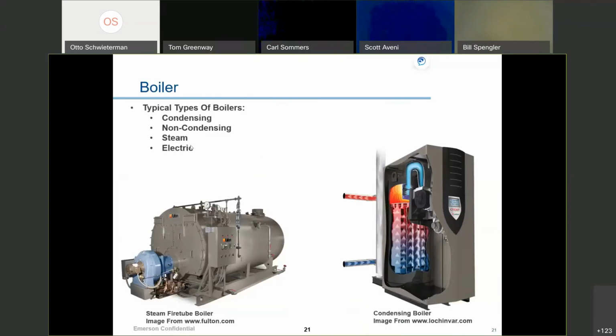I'll come back to this another way. We don't really see straight electric resistance boilers. Typically, we can see a heat recovery chiller be about 3 times more efficient than standard, 100% electric resistance heat would be. That's why you don't see too many simple electric boilers making hot water. That'd be very inefficient and very expensive also.